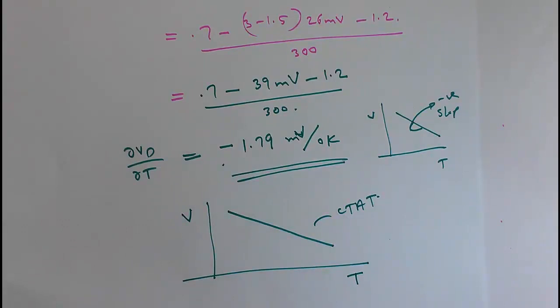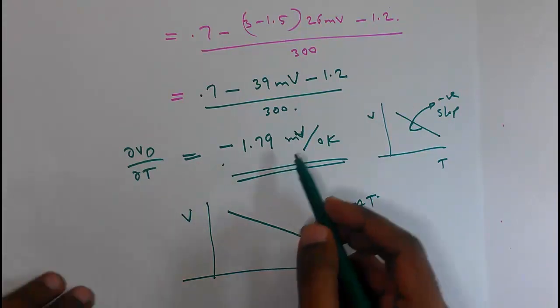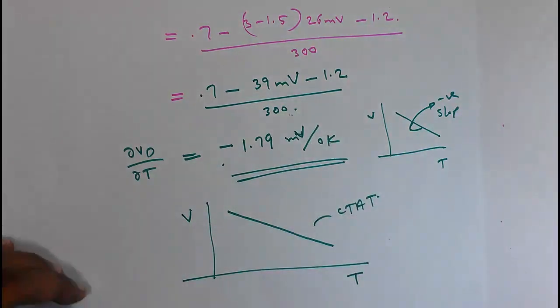So if you consider the voltage across the diode is 0.7, then you will get one value of the slope. If you consider the voltage across the diode as 0.75 or 0.8, then this value will vary. So we can confirm the value only after the simulation, how much Vd is coming. And again, this slope is dependent on the temperature, so you will not get a constant slope.